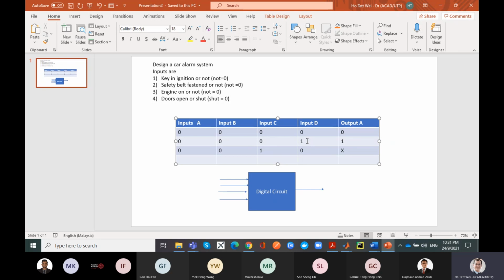So you see these kinds of toy problems, A, they're not very useful. B, you will almost always find some way where, if you specify in this way, it's not satisfactory. Why? Because there needs to be an element of time, of sequence, to make designs useful. So here, like I said, this branch here, as we've reasoned out, it's not very useful, because if you implement this logic, the minute you open the door, after you shut the engine, everything, your car stops, the minute you open the door, the alarm will sound.